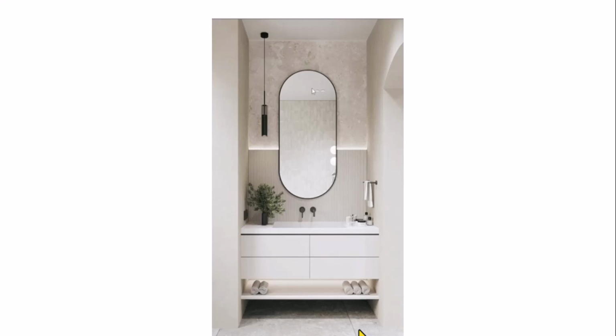So let me first explain to you the dimensions of what we intend to create. The width of this design, that is from ear to ear, would be 1200 millimeters, and the height, that is from the ground to the ceiling, would be 2600 millimeters. Then we'll put this marble slab 150 millimeters from the ground. And this slab, the thickness I want it to be 25 millimeters. Again, this height will be same like this, that is 150 millimeters.